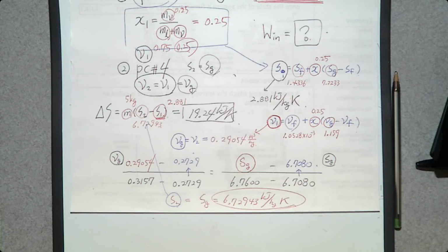So, what we learn from this problem: when we have a phase change material such as steam, we can use a table to evaluate entropy S. So when you have a phase change process number 3, we used linear interpolation to determine specific entropy S. When you have steam or refrigerant such as R134A, or water or refrigerant, you can assume it may undergo phase change.